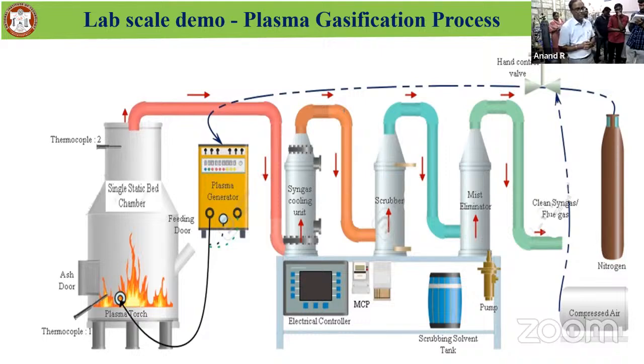It is a hot thermal plasma system, and also an equilibrium one. We are maintaining the equilibrium, that means the electron temperature is equivalent to the ionized gas temperature. The principle of working is that we create the spark. The total system is covered with nitrogen, so the spark will penetrate into the nitrogen. Nitrogen is converted to ionized gas. The ionized gas is used for heating the raw material.